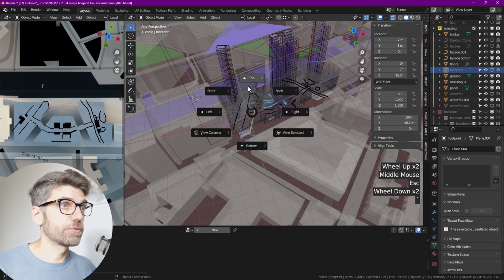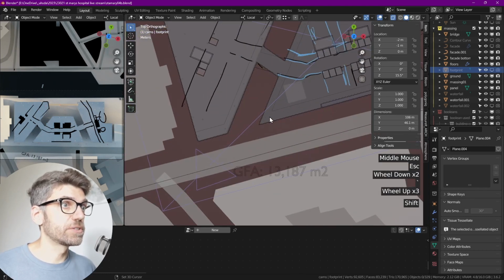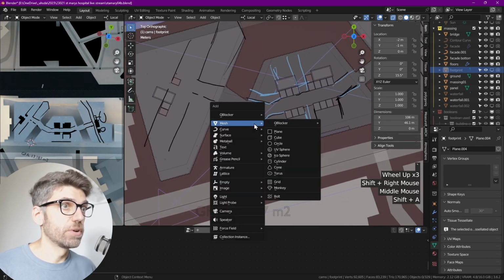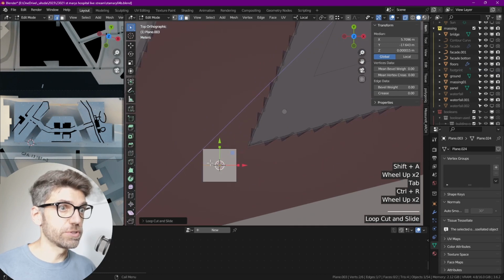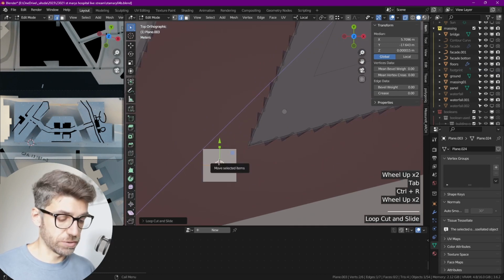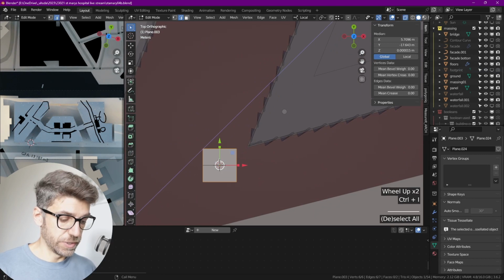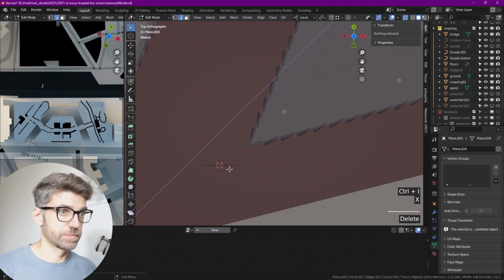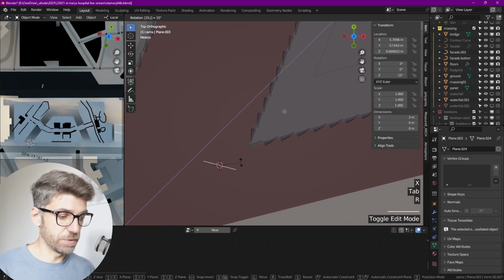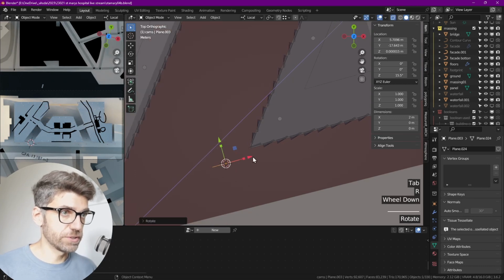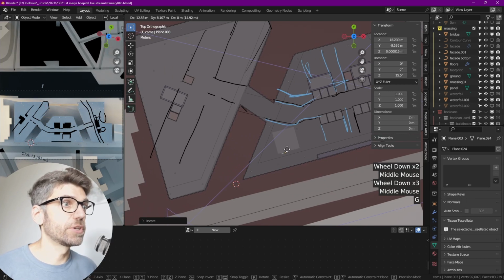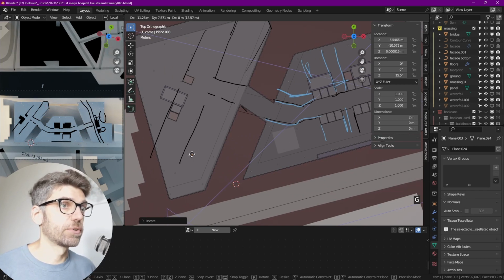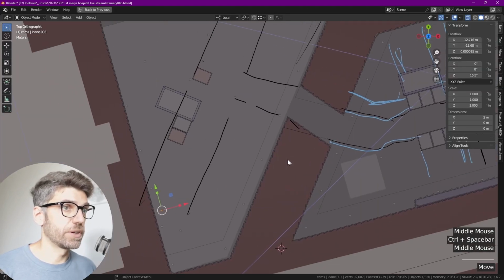So now if we go to our floor plan, we're going to start with 0 or somewhere near 0 and start creating planes, start creating walls. And the walls are just going to be edges. So let's go ahead and delete those edges. Now let's rotate this 15.5 degrees in the negative direction so that it aligns better with our floor plates. So now we're going to do the upper floor. We're not going to do the lower floor yet, but we're going to start doing the upper floors. And let's start over here.